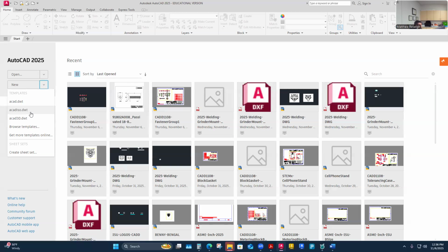It's going to take me a lot of time to create a template and have it customized. In an industry, we may have to be following an ASME standard, so there are real strict things on drawings. The text size has to be the right size. The dimension styles matter. All my font and all of this is really controlled. So I do all that front loading in a DWT file, and now it's ready to create drawings from it.